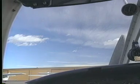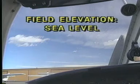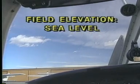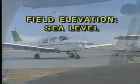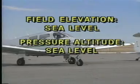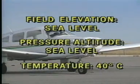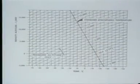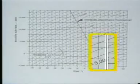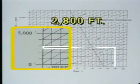Imagine that you will be departing an airport located at sea level. If standard atmospheric conditions exist, your airplane should perform as expected for sea level operations. Let's assume that the pressure altitude is the field elevation. However, the temperature is 40 degrees Celsius, or 25 degrees above standard. By using a chart or flight computer, you'll find that at 40 degrees Celsius, the density altitude is approximately 2,800 feet.